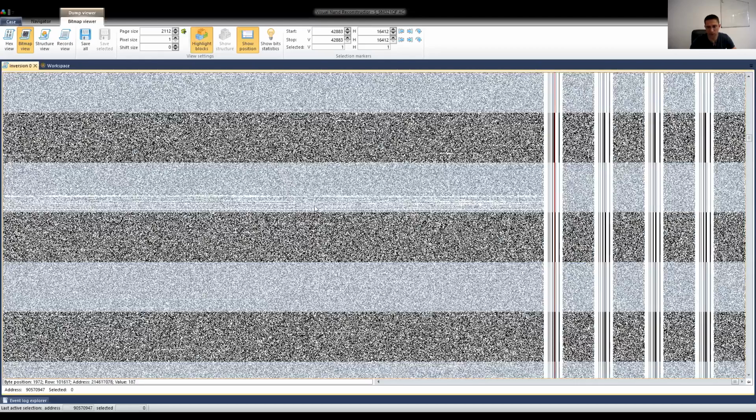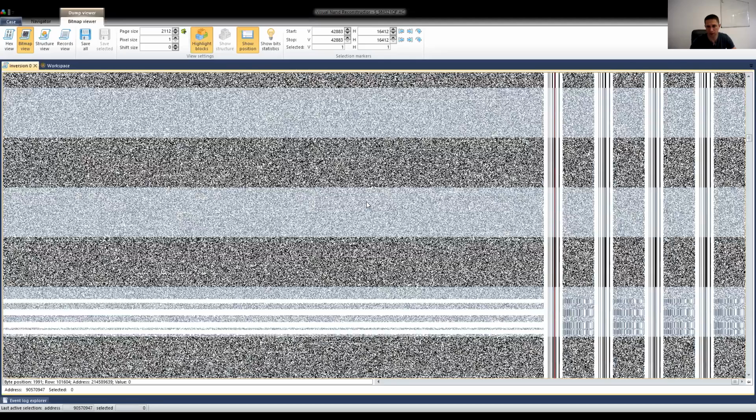and these lines may tell us if the multiplane was used or not. And here we can clearly see that multiplane wasn't used. Or, for example, this block. We can see just noise here, but then some more whitish pattern in the second part. Also different patterns in the first part and in the second part. So this is how data looks when we don't have multiplane page allocation.